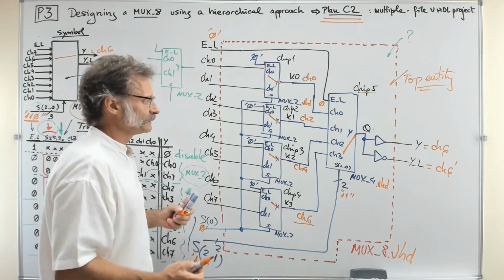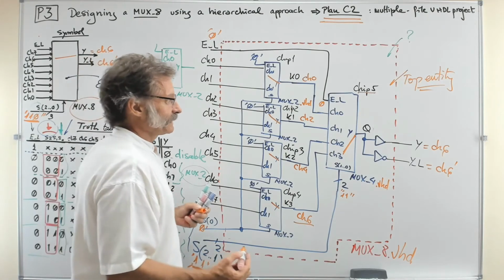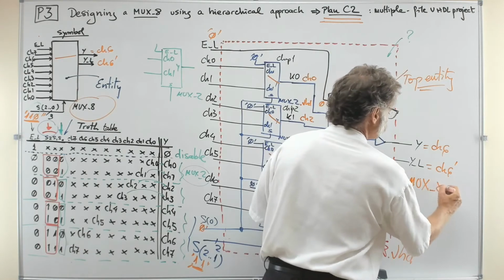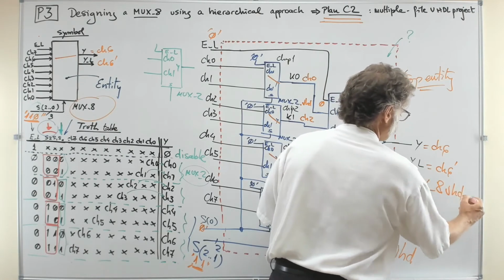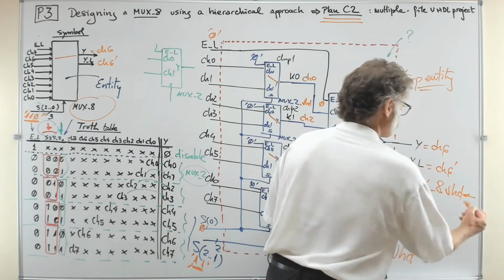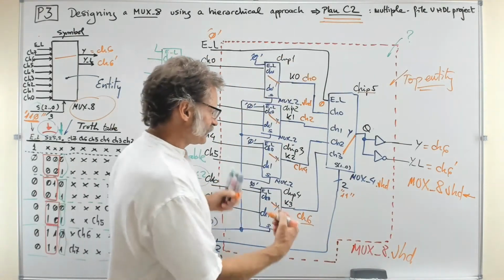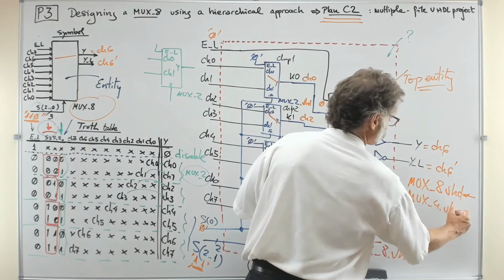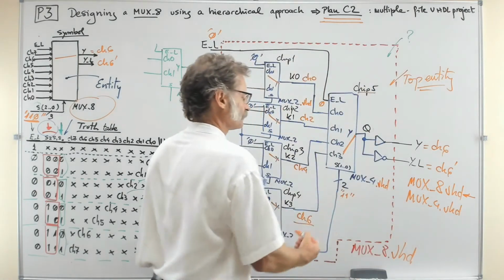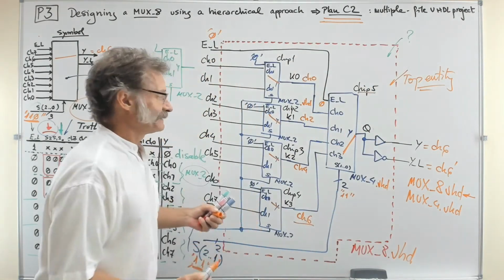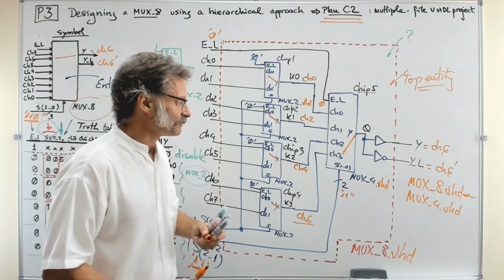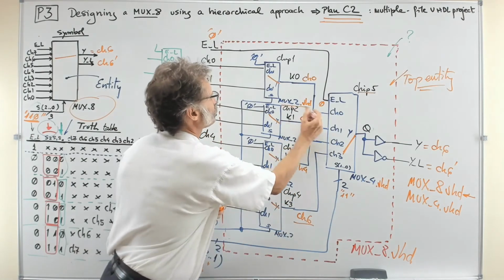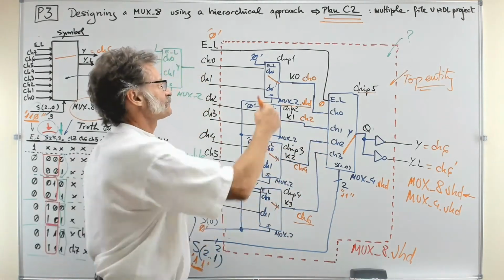So how many? Well, I guess that you are inventing here, that you have to invent the MUX8.vhd, that's naturally the top project. And then you have to take with you another file, the MUX4, because the MUX4.vhd is a component of the circuit. And then there is another circuit that is used more than once. You know, the MUX2 is another component, and it is used several times.